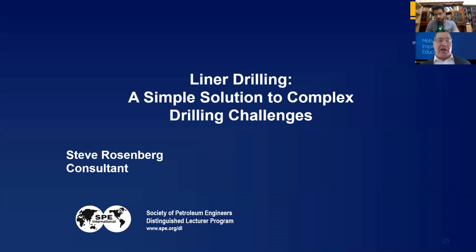You bring up a great question. I love those questions. This actually happened in a job I was involved with. They didn't clean the active pits out after they drilled out the float equipment. So we picked up the liner, started going in the hole with the drilling liner, and what do you think happened when they started taking suction out of that active pit? All that debris from the float equipment plugged off the floats. It was a good thing we only got to about 600 feet below the derrick, and we had to pull the liner out of the hole.